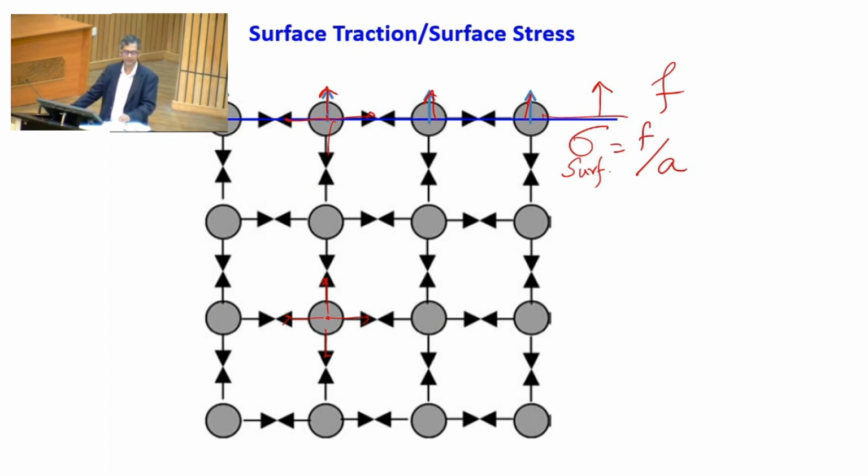So, obviously, the surface free energy or gamma will depend on the amount of stretching, epsilon s. How much these bonds get stretched because of this force F acting on them will decide the surface energy also, much like the stretching of a rubber screen.